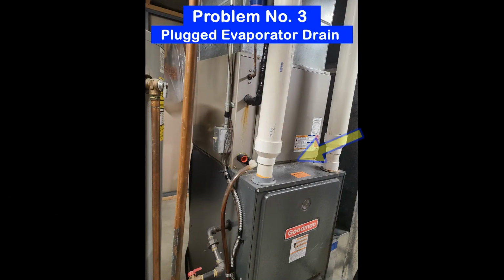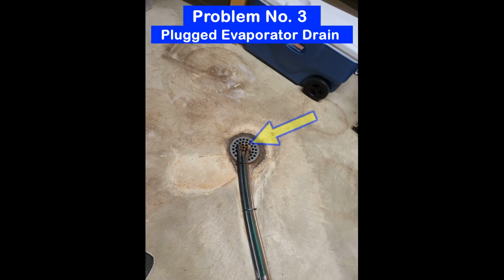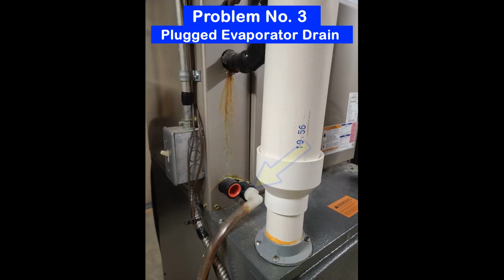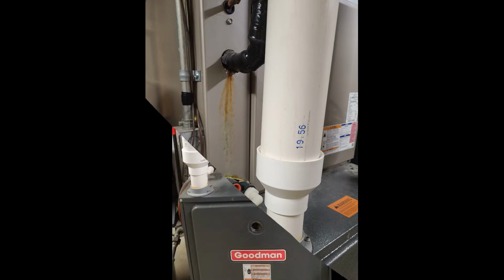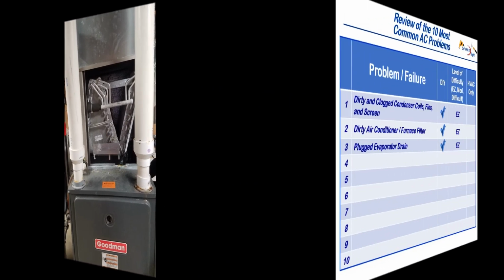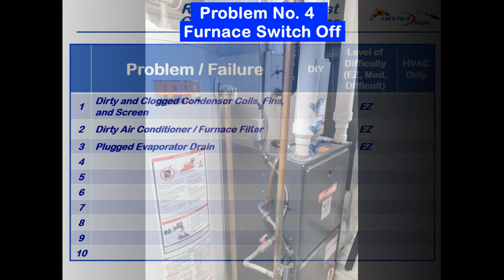If you notice water leaking from the base of your evaporator drain pan and no water coming out of your drain hose, you most likely have a clogged evaporator drain line or blocked fitting connection. Consequently, I recommend that you remove the line and clean it. I also recommend that you clean out its fitting and clean the visible dirt, mold, and rust from the drain pan. Be careful not to damage the evaporator. It's a very expensive part of your air conditioning system. This, in my opinion, is a very easy do-it-yourself task.